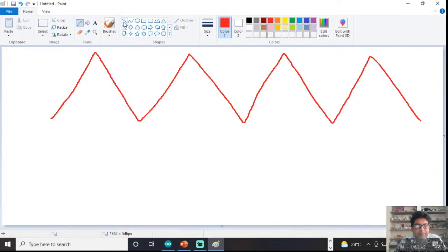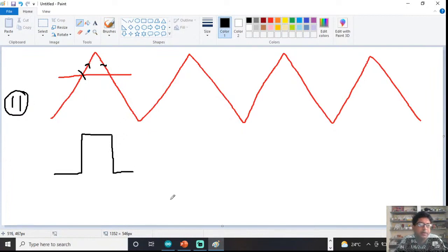Now if I set a value of this output compare match like this, what output will we get? If we set 1 1 in that 2-bit, then when the compare match occurs, the pulse will be set and remain at high state; this is the up counting, and while down counting, when it matches, it will be cleared. So you will get a PWM like this.